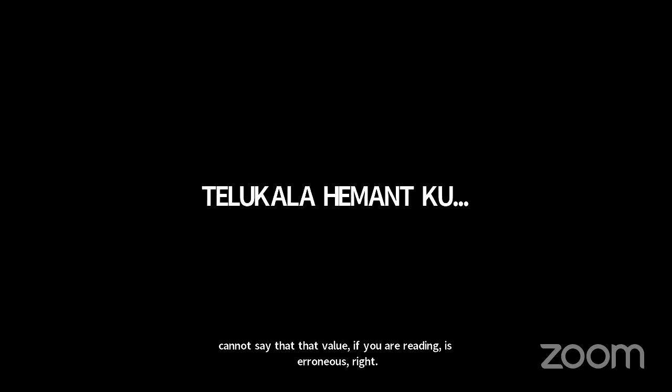You got my point? Yes, ma'am. So when you connect that resistance value in the Wheatstone bridge, let's say R1 is now changing from 100 to 1K, 100 plus 1K, that 1K change corresponds to the VAB. Before, VAB was 0, right? In the balanced condition. Now the change will only correspond to the output, not the whole.